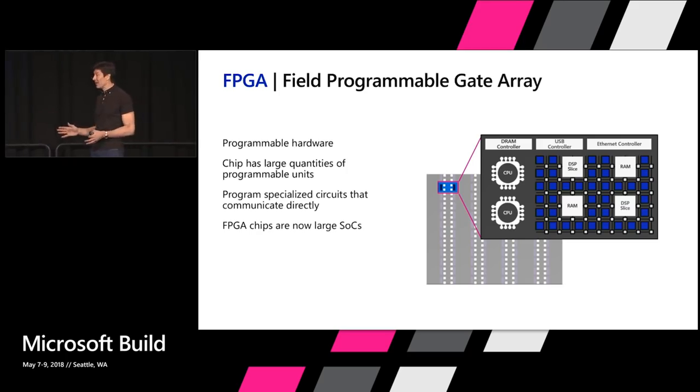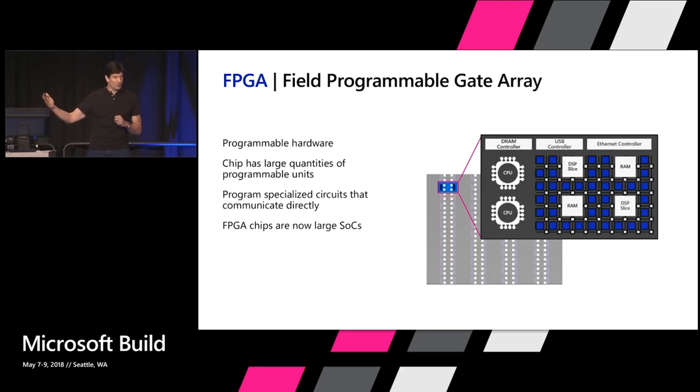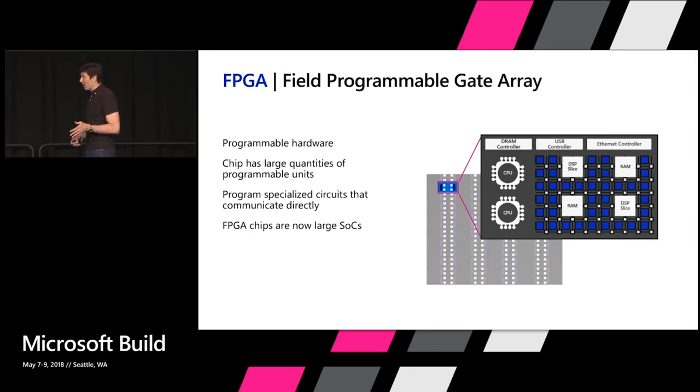I don't have time to do that here, but effectively, if you take a look at the spectrum of hardware, it goes from general purpose processors like GPUs and CPUs, down to ASICs, which are custom hard-coded pieces of silicon with algorithms basically embedded in them. So very fixed function, but once you're in fixed function, you're very low cost, and you're very low power. And you also get great performance because it's just been optimized for that particular algorithm.